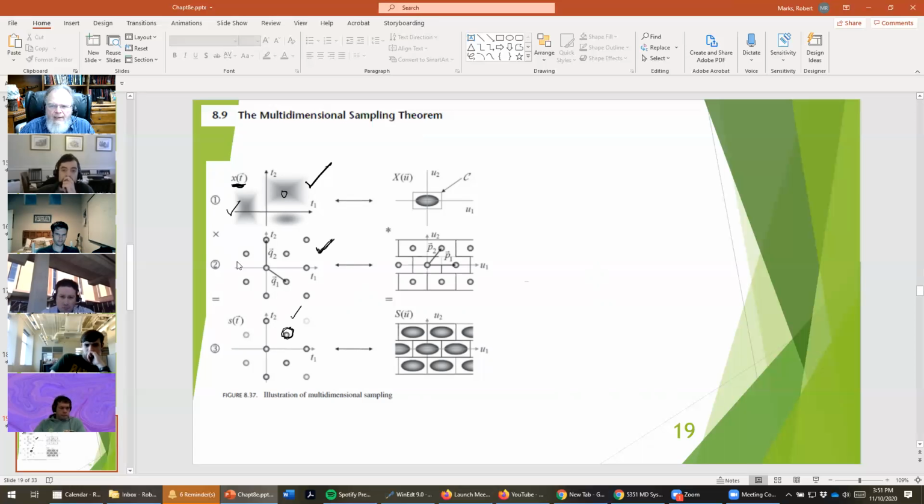And this is very intuitive, right? We take an image, we multiply it by a sequence of Dirac deltas, and we get what we call the signal of samples. Okay, that's S of t. That's the signal of samples. Well, this is very intuitive. What is not as intuitive is what happens in the frequency domain. In the frequency domain, we take the one-dimensional spectrum, and of course we've just determined that this two-dimensional array of Dirac deltas corresponds to a two-dimensional array of Dirac deltas over here, correct?